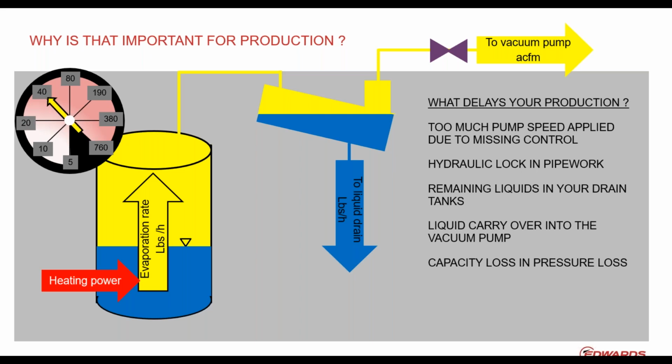But if you apply too much vacuum during the running distillation and basically take more evaporation out than the heating power supports, the temperature in your reactor goes down. That process can freeze off the entire surface of your liquid. It just freezes it off. The tricky thing is your gauge in your reactor still shows the pressure is going down. Everything looks great, but it isn't.